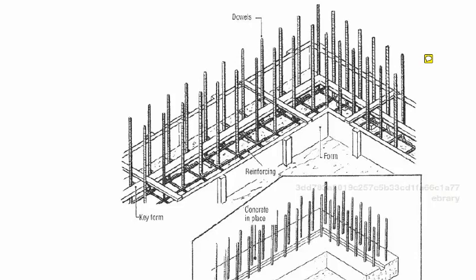You need a certain thickness of concrete between the exterior of a wall or footing and the steel to protect the steel reinforcing rod. Otherwise, water, chlorides, other chemicals will get in there. If the separation is not thick enough, they will rust the steel. When the steel rusts, it expands, it gets wider. And it's that expanding that then pushes the concrete and spalls the concrete off, and then your project is on its way to ruin real quick.